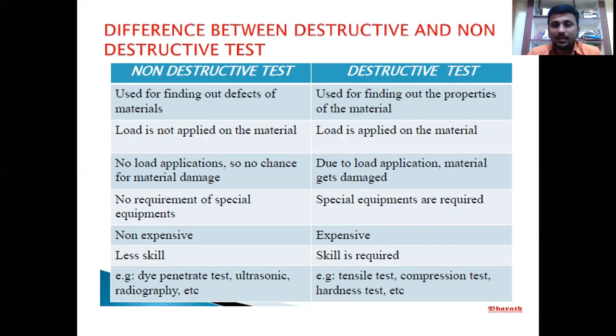These are NDT test methods. There are many methods, and some major ones are dye penetrant, ultrasonic, and radiographic tests, which are easy to operate. But in destructive tests, like the tensile test, compressive test, and hardness test we learned in the first two slides, you need high skill to operate and inspect.